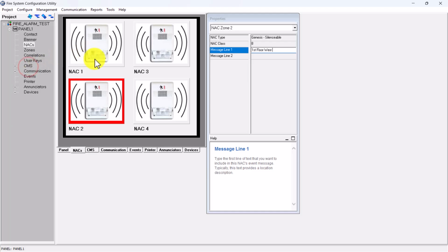Central station, we're not connecting this to a central station, but here in the telco account one is where you will put your 4-digit account number, your primary, and your secondary receiver. And also if it's reporting by device, by zone, or by event. Usually we would report it by device type. That's contact ID. So every point that's installed on a fire alarm control system, contact ID is identify every device that's on a fire alarm system. So if it's device 1 all the way to device 100 and whatever that description is, it will be sent over to central station.